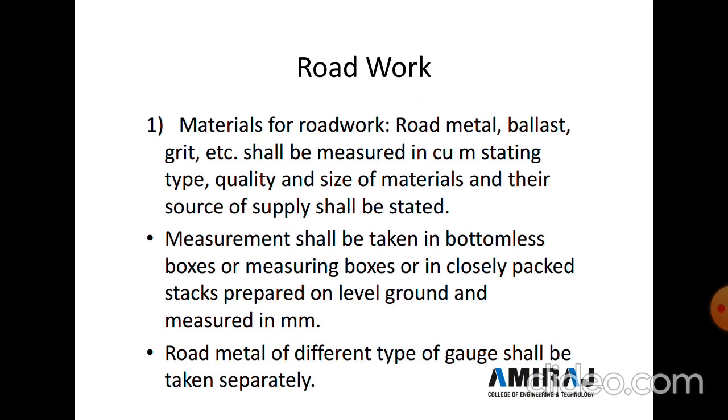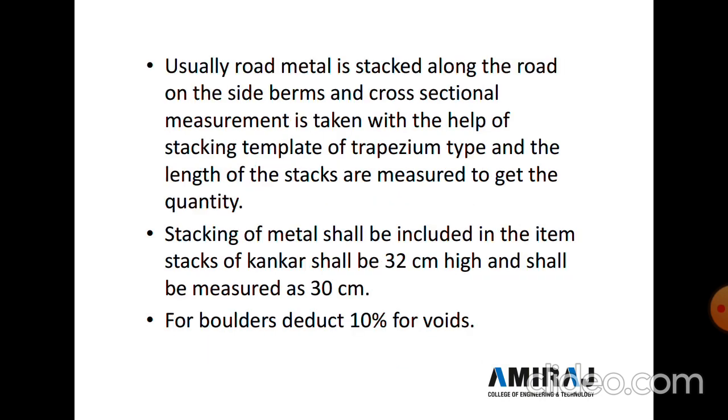Road metal of different types and gauges shall be taken separately. Usually road metal is stacked along the roadside on the side berms, and the cross-sectional measurement is taken with the help of a stacking template of trapezium type, and the length of the stack is measured to get the quantity. Stacking of the metal shall be included in the item. Stack of the metal shall be 32 centimeter in height and shall be measured as 30 centimeter. For boulders, deduct 10% for the voids.